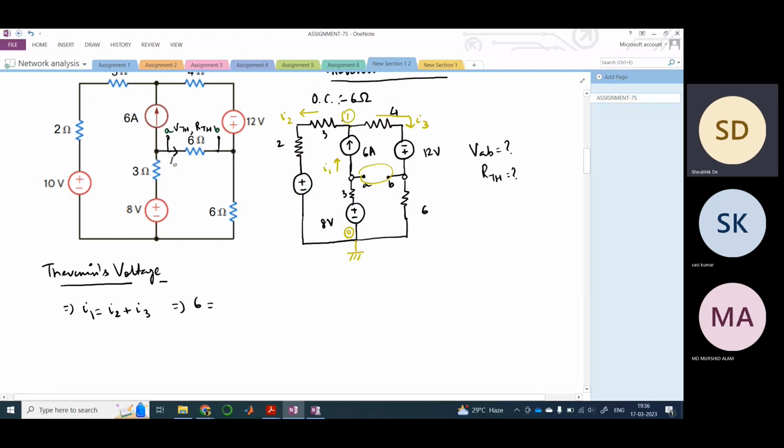Now, what is I2? I2 is the current that is flowing in this node, and this is 10 volts. So, what would be I2? It would be (V1 minus 10) divided by 2 plus 3, because there are two resistances here. And what would be I3? It would be V1 divided by...